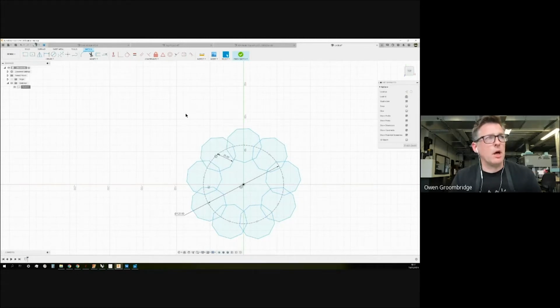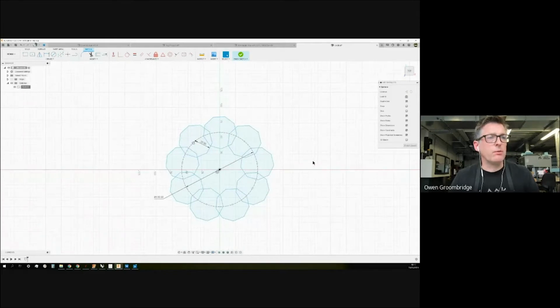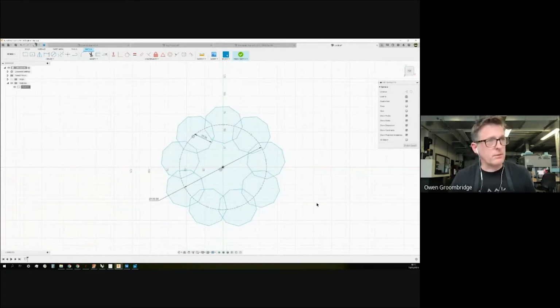You could even sweep something like that, although it might be a good idea to trim the bits you don't want. Or you create a sketch like this, your base sketch, so to speak, and then you create duplicates of it by projecting onto other sketch planes, and thereby you can select the elements of those sketches you want for that particular sketch. Okay, so that is revolving, heavy on the processor for some bizarre reason. All right, let's go back.